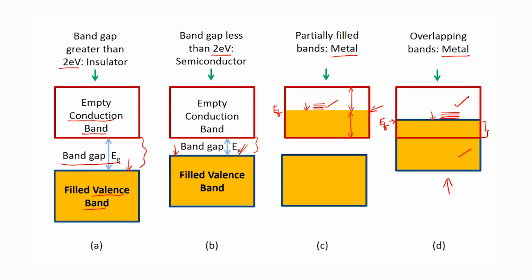In the case of semiconductors and insulators, especially what are referred to as intrinsic semiconductors, and we will talk about them in just a moment. Intrinsic semiconductor simply means it is pure, it does not have any impurities in it that have been deliberately added. It is not a doped semiconductor, it is a pure semiconductor. So, in those conditions you can still define something called a Fermi energy level, and that definition is necessary because it helps us figure out certain other behavior of the materials, which I will talk about in just a moment.